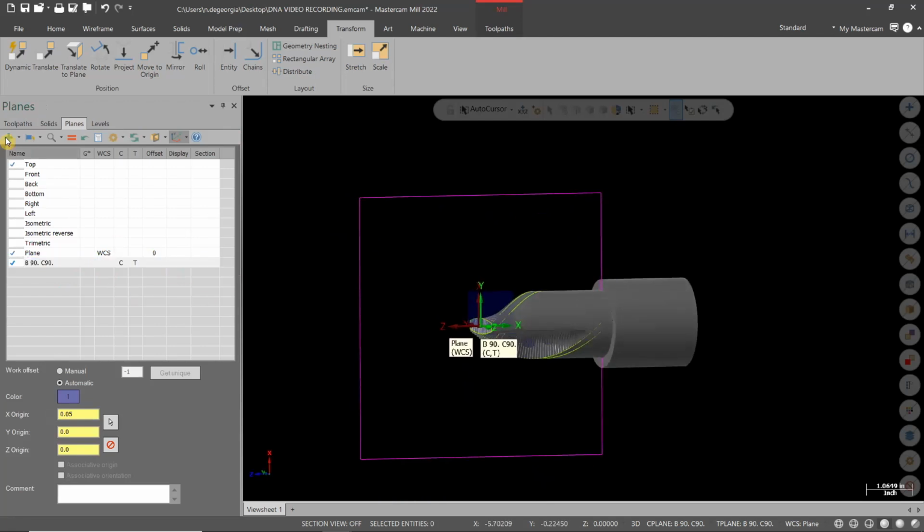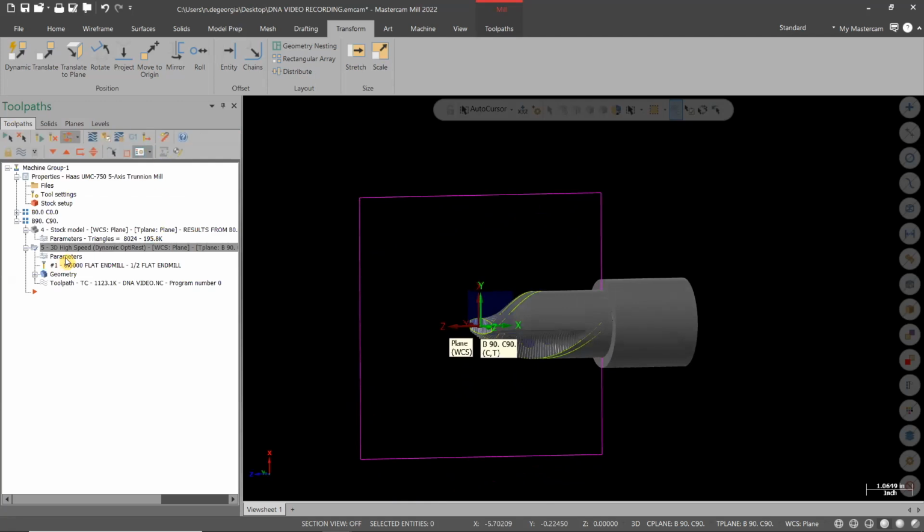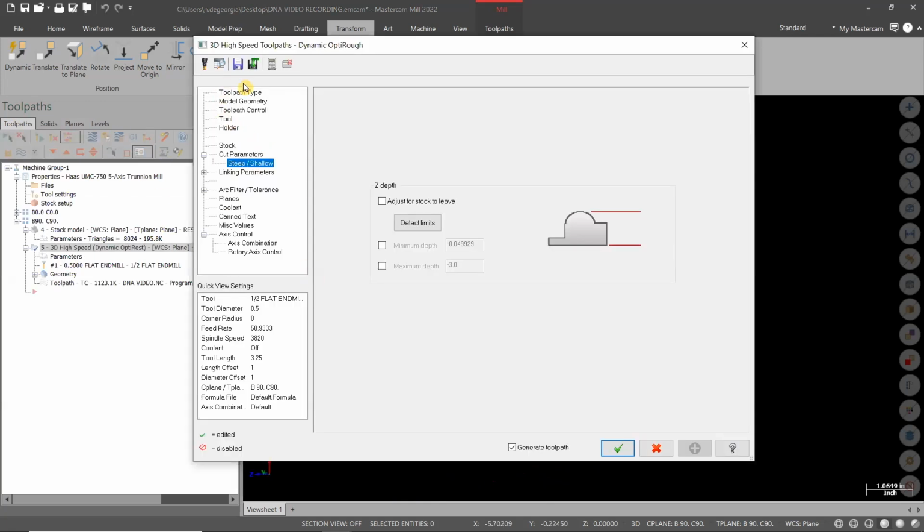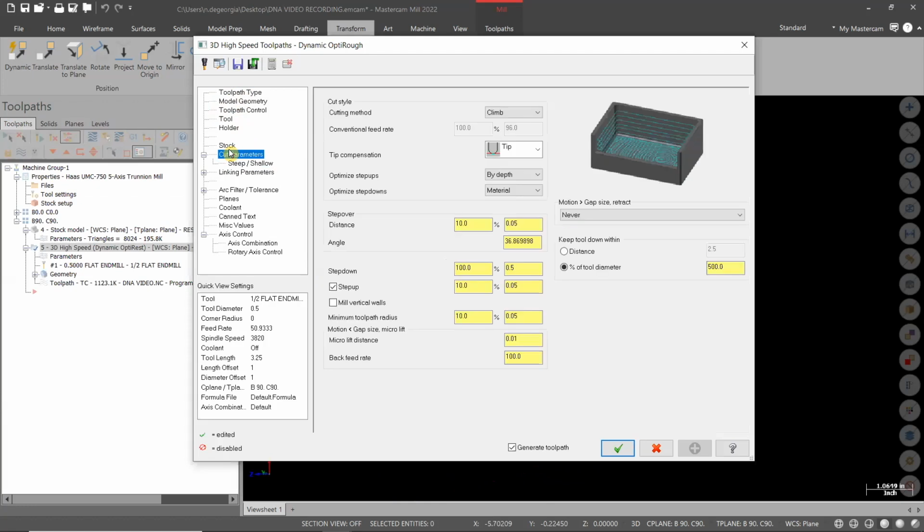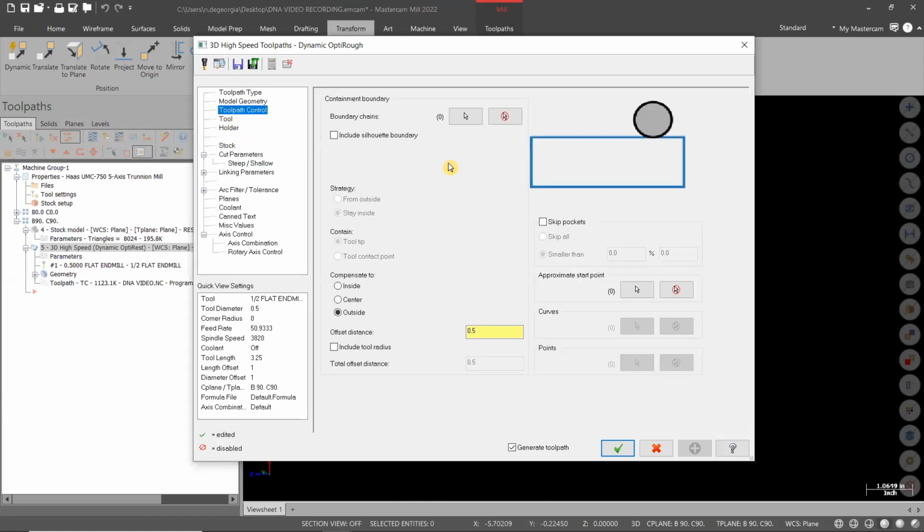After adding the machining boundary, I will now modify my steep and shallow conditions and also change my leads that I had for my vertical roughing. When complete, I will check out the toolpath and see if the boundaries are in place.